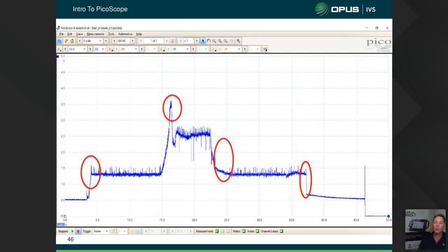And that residual pressure is because all my injectors are closed. What I should see over time, over the next 5 seconds, is that fuel pressure slowly bleed off, right? I shouldn't see it drop all the way back down to that 0.6 volt like we did here instantly. If I turn that engine off and it drops all the way back down there, then I've probably got a leaking injector. And that's the best way we can see. This car was good. So we've seen the fuel pressure bleed off really slowly. And this point here is where the ECM has actually shut down and removed power from the fuel rail pressure sensor. So that's a pretty good test.